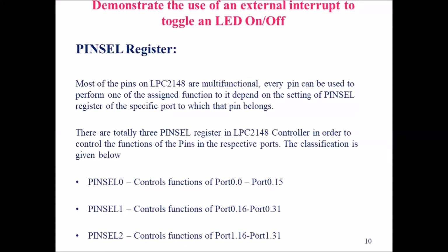As I told, there can be a single function associated with a pin, or a maximum of 4 functions. At a time, only one function can be executed through that pin. All 4 functions cannot be executed at a time, only one function can be executed, and that function should be selected by the pin select register. There are a total of 3 pin select registers available in the LPC2148 microcontroller in order to control the functions of the pins in the respective ports.